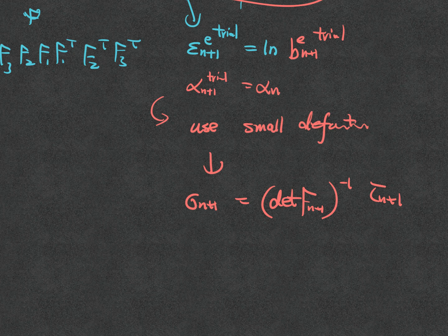Eventually, I never deal with the complicated algebra of the multiplicative decomposition. I actually just use the small deformation theory, but I get the result of the large deformations simply using the logarithmic and exponential mapping. Okay, what is the limitation of that? If you have kinematic hardening or internal variables that are rotating a lot, you need to consider that as well. This only works for the isotropic case in general. Does that make sense?